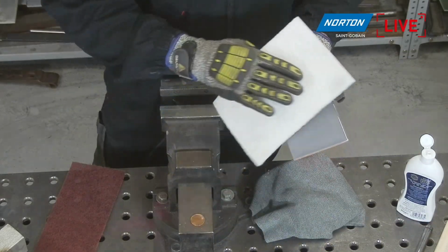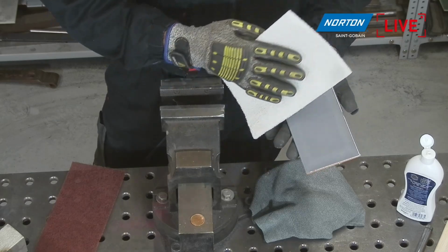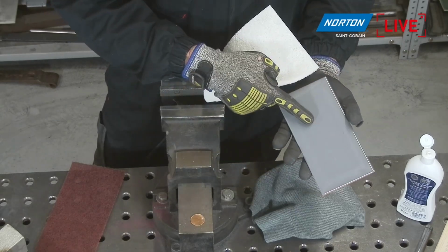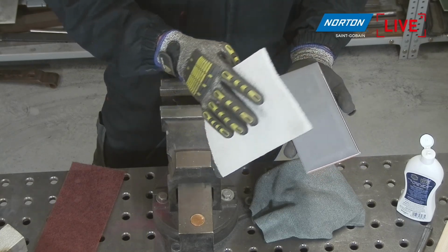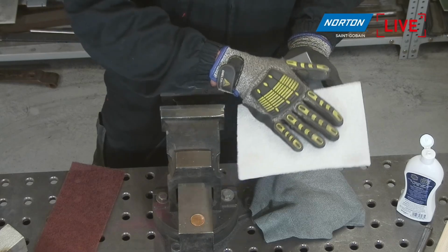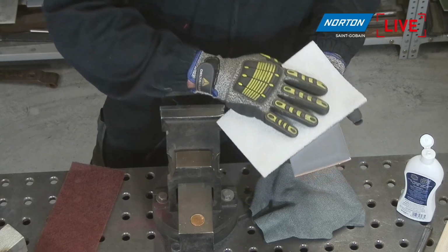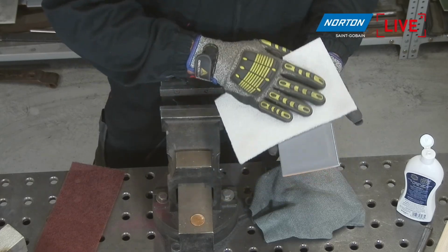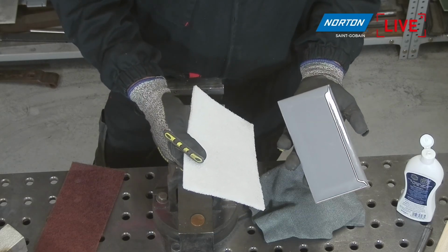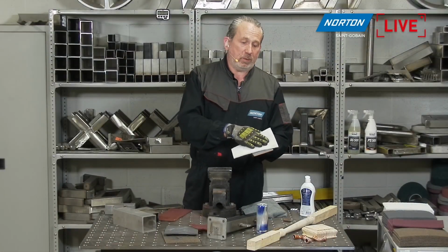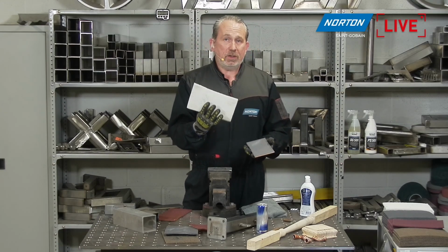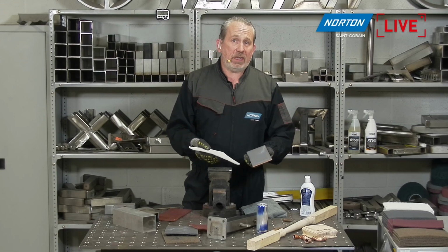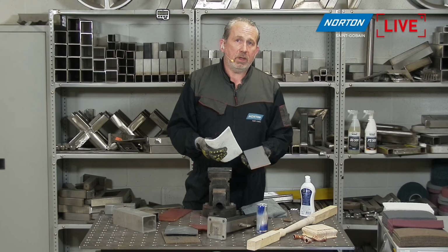The white hand pad is absolutely perfect for this. Again, it's not abrasive. You're not going to put a scratch into the surface of the ceramic. No matter how long you rub it for, it's going to stay good. But it's able just to take off that powdery white grout that's stuck to the surface of the tile without damaging anything, or also without gouging into the grouted edges around. So really good, and that's a very tedious application, which this can speed up a great deal for you.